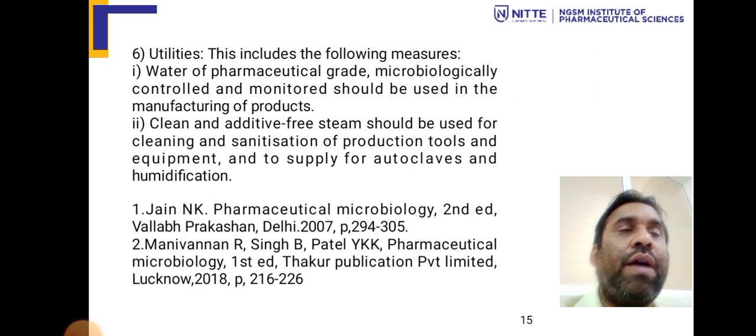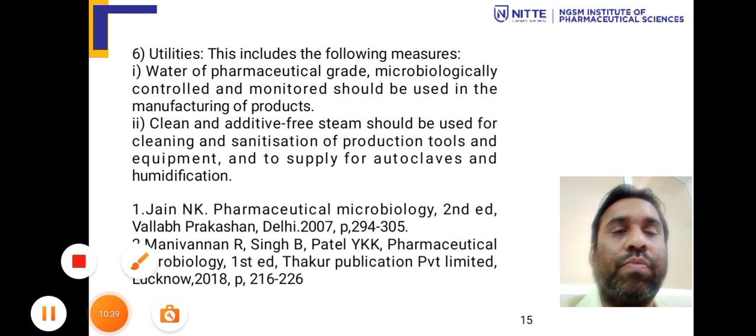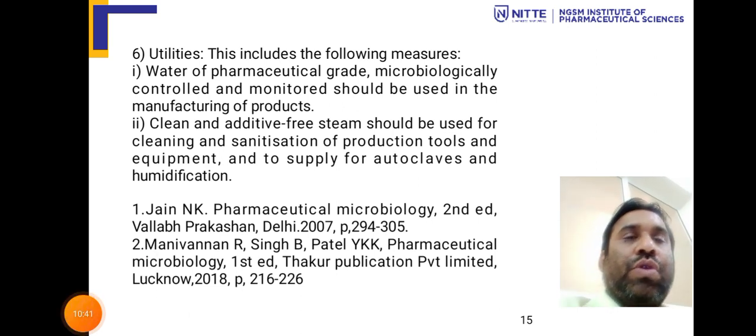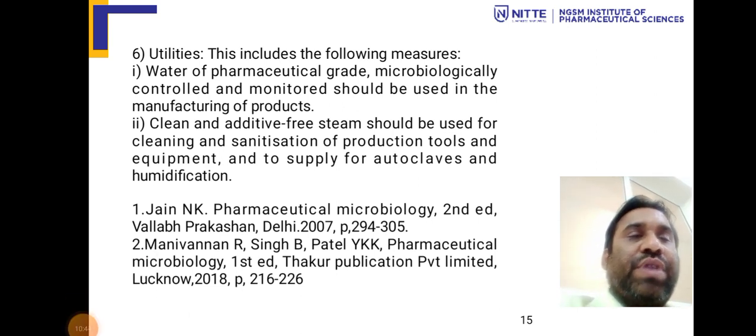Utilities. These have the following major points: water of pharmaceutical grade, microbially controlled and monitored, should be used in manufacturing products. Clean and additive-free steam should be used for cleaning and sanitization of production tools and equipment, and to supply the autoclaves and humidification.